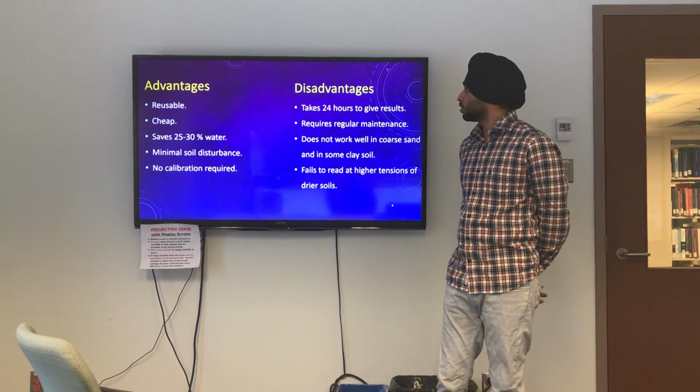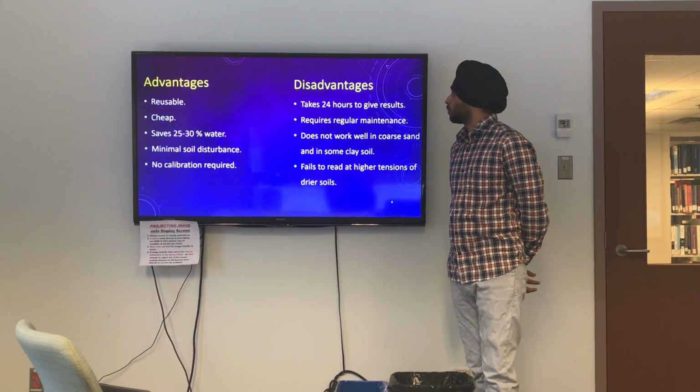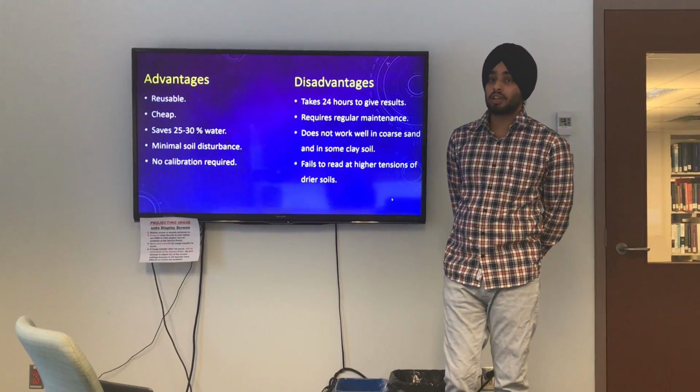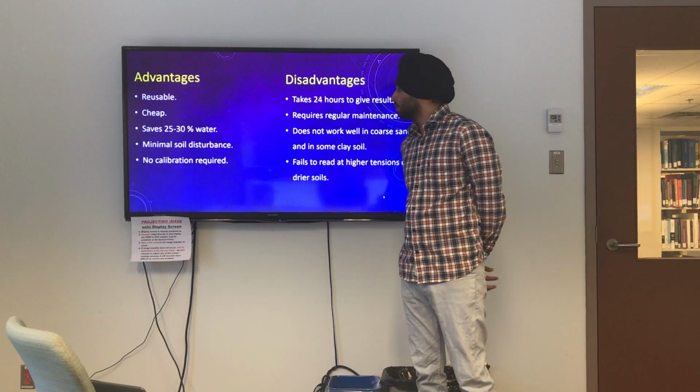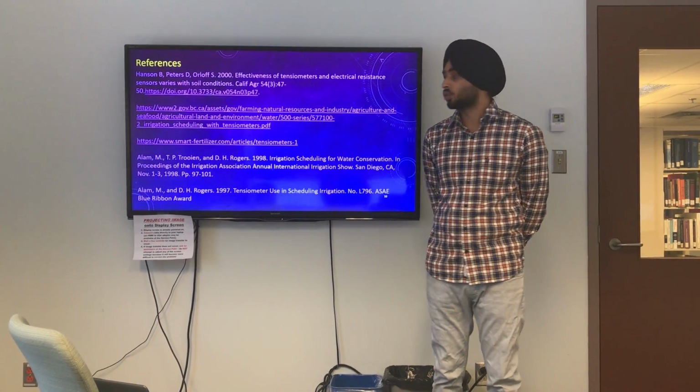There are also disadvantages. It takes about 24 hours to give a result. Also, it requires regular maintenance. It also doesn't work in coarse sand and in some clay soil.